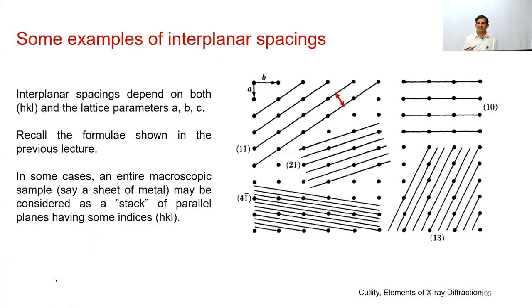So like we discussed yesterday, what was interplanar spacing? It's just the shortest distance between a plane passing through the origin and the same plane of that same family, which is closest to the origin. Or alternatively, a simple way of looking at it would be whenever we say a plane HKL, it is not a single plane, but it's always a set of parallel planes. For example, if it's 100 in a cube, then it is all the 100 faces which together form the set of 100 planes, and the shortest or perpendicular distance between them is called the interplanar spacing.